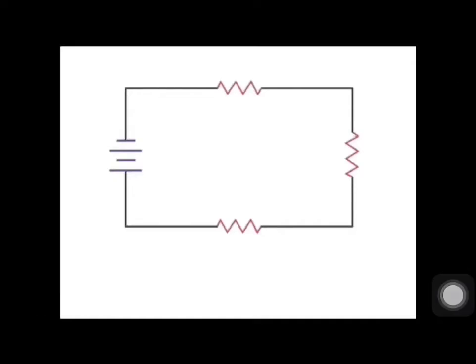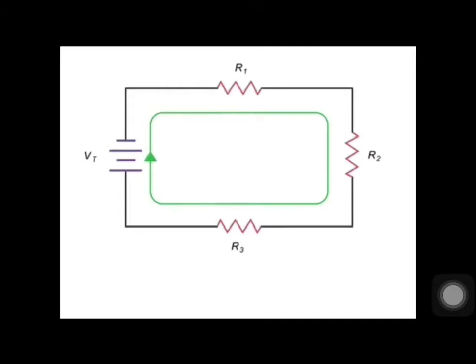Connected along a single path with the current flowing in the same direction through each component. For instance, if the source current in a series circuit is 5 amps, then no matter where along the circuit you take an ammeter reading, it will also register 5 amps.